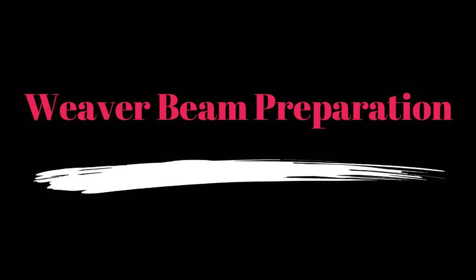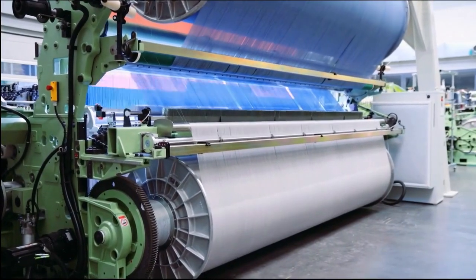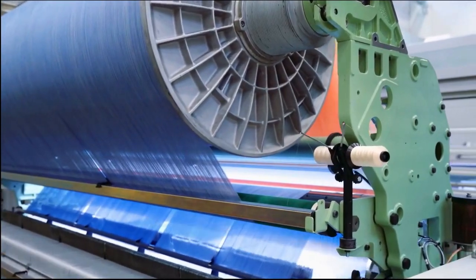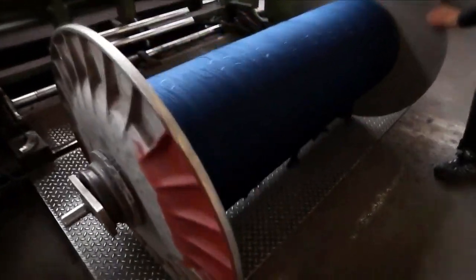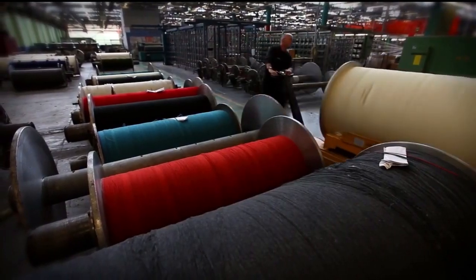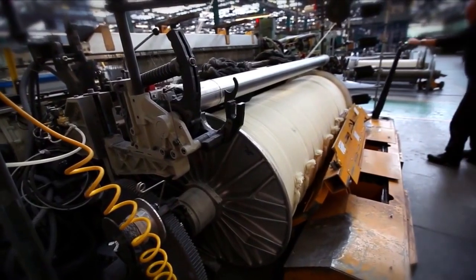Weaver beam preparation. For long runs of gray fabrics, beam warping is used. As an intermediate stage, warper beams are produced that can contain up to 1000 to 1100 ends. Then 6 to 12 warper beam threads are merged at the slashing stage and wound on a weaver beam.